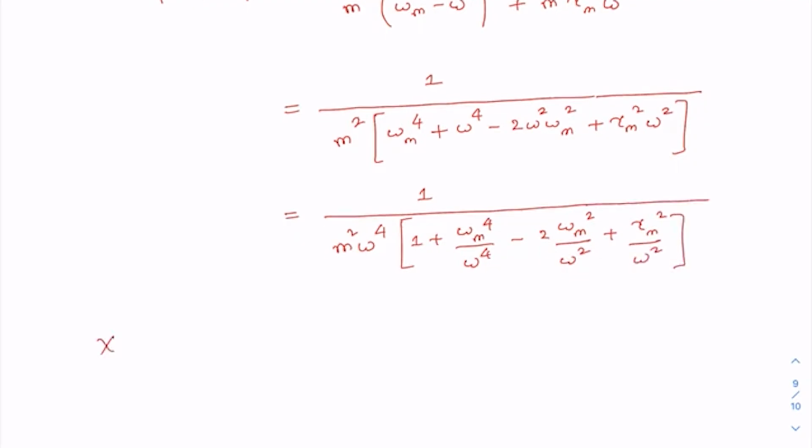So the modulus of the mechanical susceptibility at very high frequency, that is omega tends to infinity, that would be equal to 1 by m omega square, as these terms will vanish. In fact, this is nearly equal to 0. What it means physically is that the oscillator essentially behaves like a free particle, and the response of the oscillator is inertial and is independent of stiffness and damping.